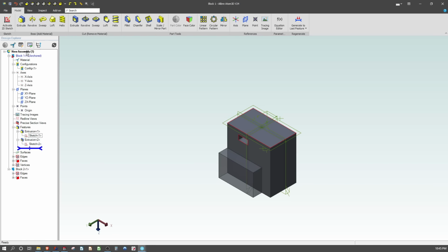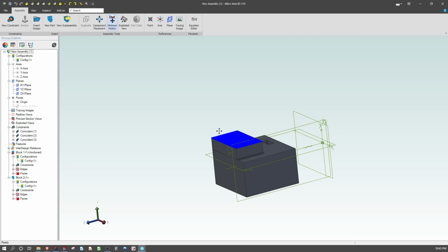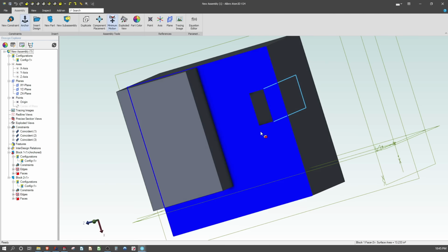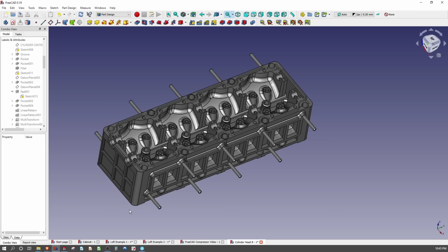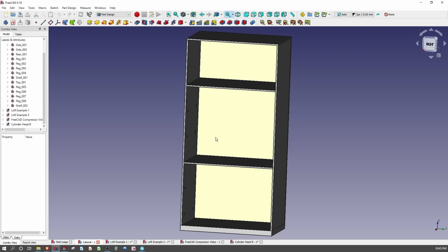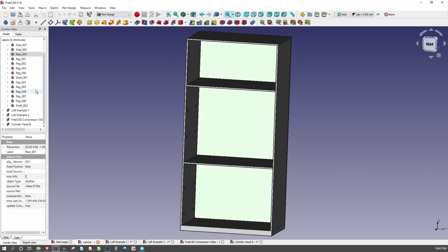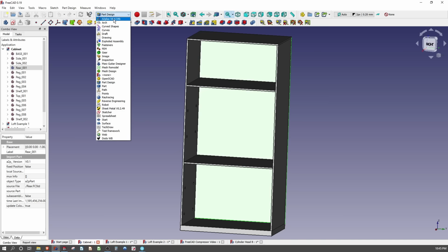and then I come to my block, we'll go back to our root assembly. There's no errors here, right? There's no problems. And that's because it's stable with redundant constraints, and it's stable with adding new features to the part. Now if I open up FreeCAD, this will change depending on which assembly you use. This was made in the A2 Plus workbench. Right, so I might go to the A2 Plus workbench.